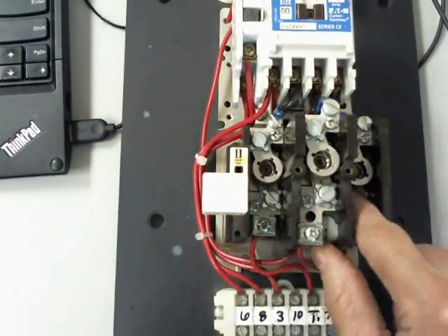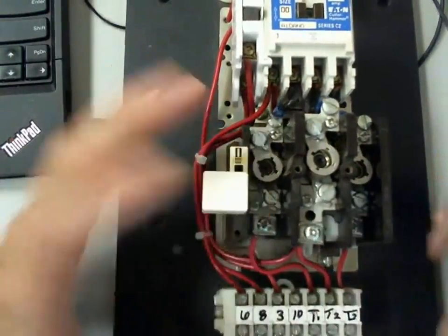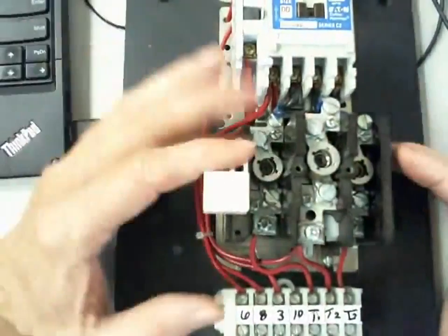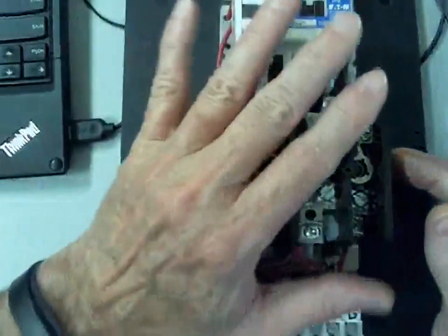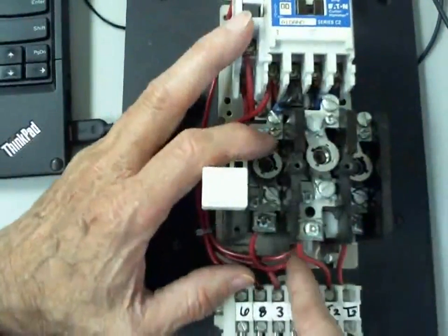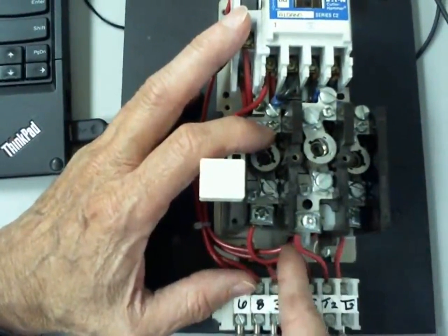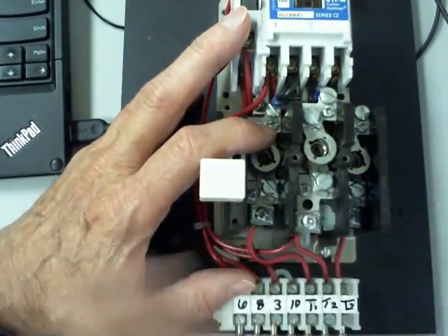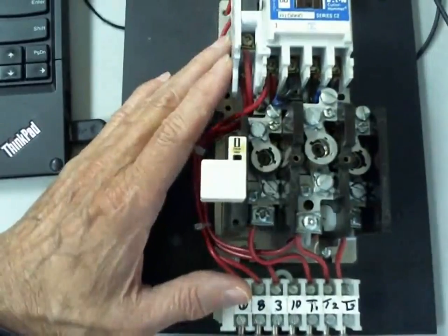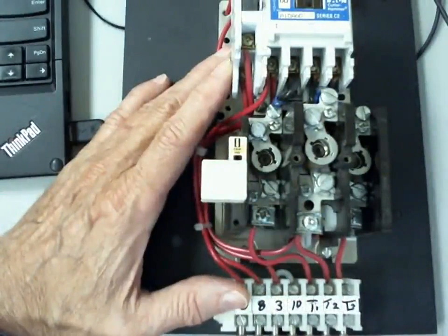And we'll look in a little more detail at how these overloads work. It's really neat. But we have one button to reset it. The old ones have multiple buttons on them. And then finally, OSHA took control of it and said we need one reset button that resets all 3 overloads inside there. In fact, on your new ones, you only have one contact. If any overload trips, it trips this one contact, right? You understand? In the old ones, you had one contact per overload. So if you see a diagram that's got one contact, that would be one like this. If it's got 3 contacts out, then it would be the old one.